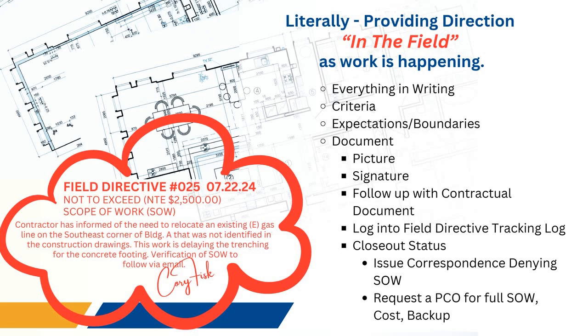overall contract. Then once we've determined this, we can determine if it's a change request, which is a change being requested on the owner, architect, construction management side of the project, or if it is going to be a proposed change request, which is going to be a proposed change from the contractor in the original contract scope of work, and therefore requires them to identify a potential cost and potential time impact of this particular situation.